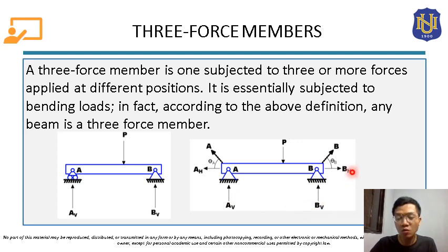But as we know, we can only generate a maximum of three equations in solving any force system. So here, this is actually an indeterminate beam. We cannot solve this using statics. But as we know, members in frames are actually three-force members. As you can recall, frames are pin connected. The frames that we're going to analyze are pin connected.